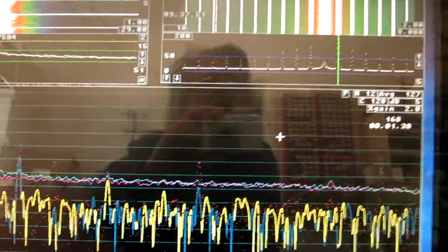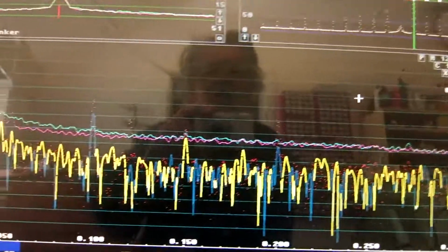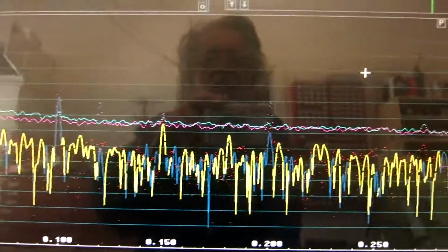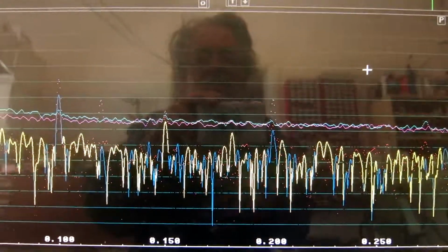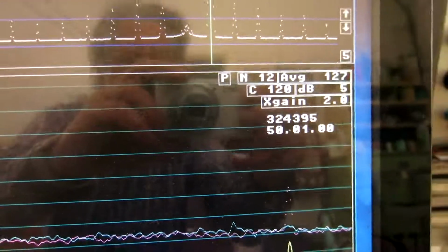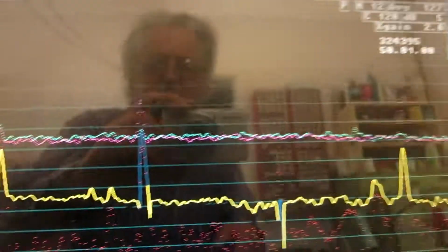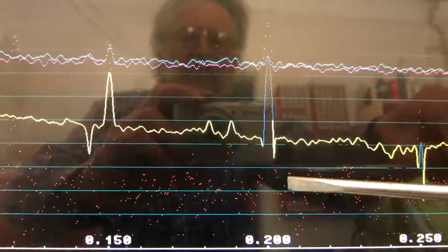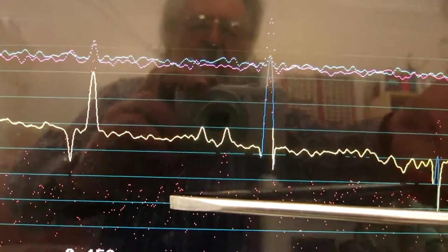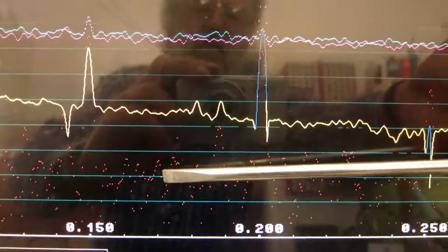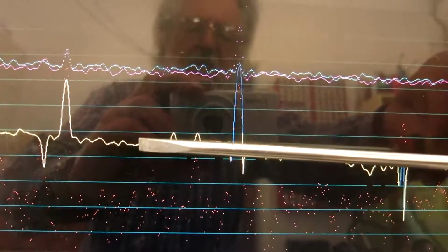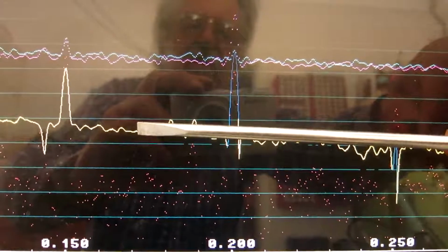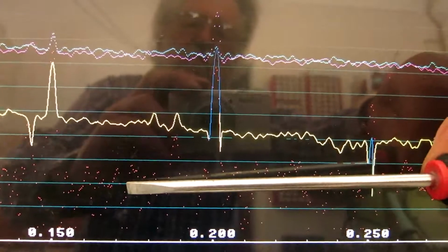This is only 1.5 minutes, and the imaginary part and the real part have the same size. After 50 hours, the signal to noise ratio, measured as the separation between the imaginary part here and the noise from the device under test here, is almost 10 dB.